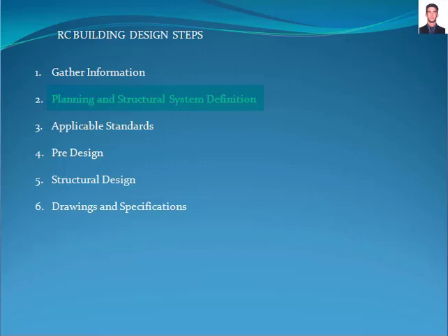But in general terms, to start any project, the first thing to do is meet with an architectural professional to review the conceptual design and get in agreement about structural materials, height of the building, height of each story, and the preliminary disposition of columns, beams, or shear walls.